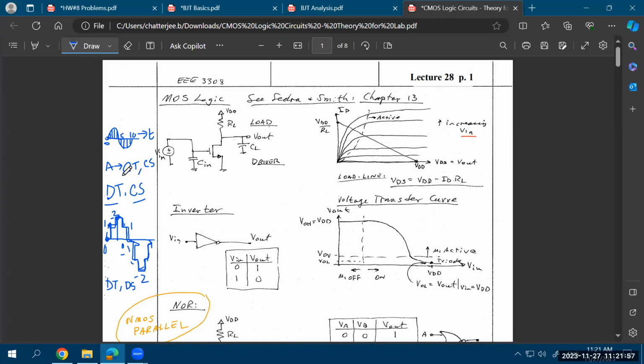So analog means you have continuous time, continuous signal. If you just sample in the time domain, that's not enough to call it digital. When you are calling something digital, then it really is discrete time and discrete signal. And many times, your discrete signal will have only 2 values. That's called binary digital logic, where your discrete signals are either 0 and 1. It can be represented with 0 volt and 1 volt, or 0 volt and 5 volts. Basically, you have 2 digital logic levels. One logic level is logic 0, the other is logic 1.